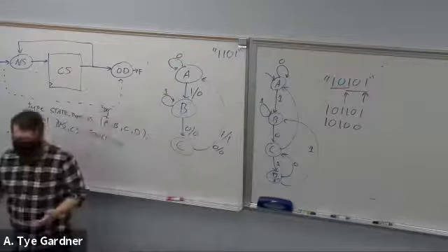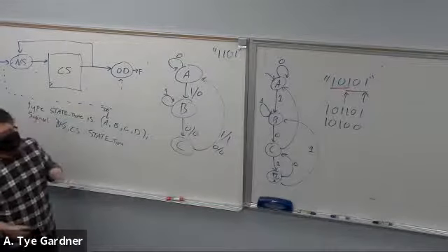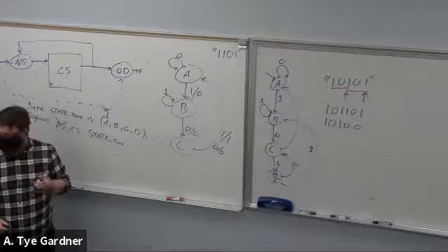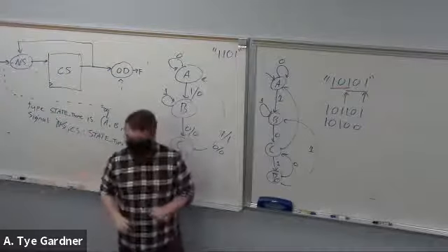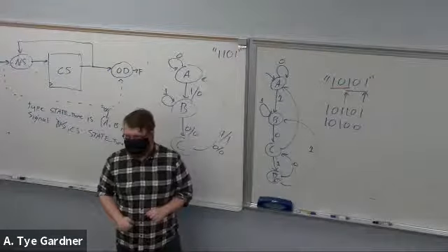So that's sequence detectors. In general, draw the path that you know you need. Draw the right path first. And so when I ask you on the exam to detect for me some pattern, you'll at least get most of the points if you just draw the arrows for the actual thing. Then you can go back and fill in the alternates. Make sense? Okay, good.